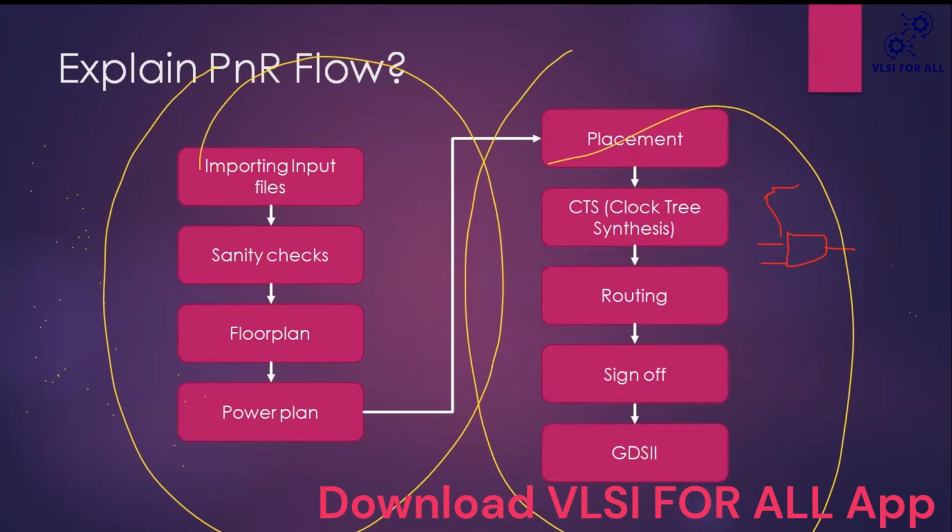But in timing driven placement, timing is the major priority. It has to fix all the timing, so it takes timing as a priority and places the standard cells in the design.